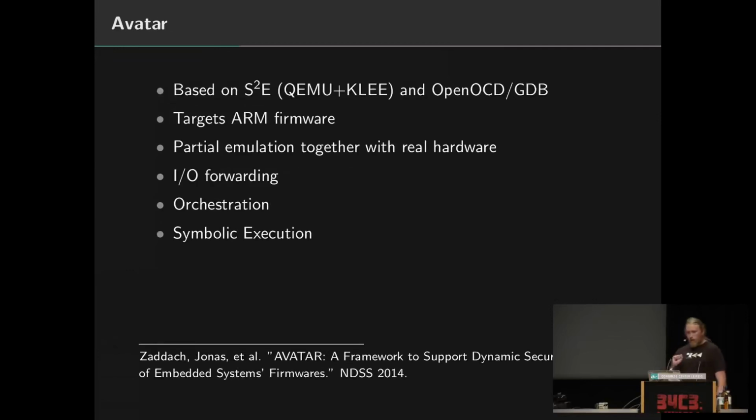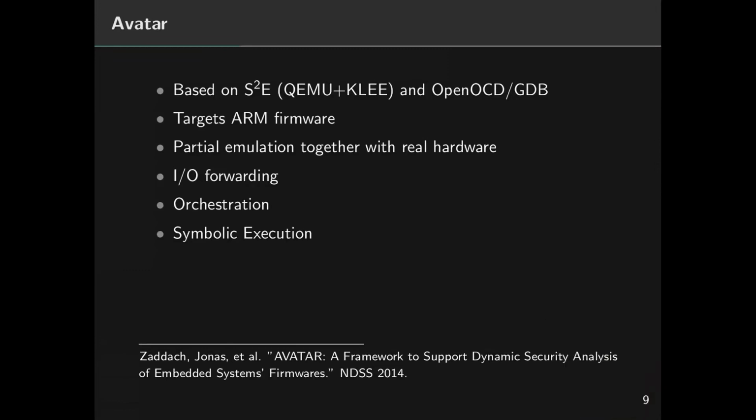So the last tool I want to talk about is Avatar, the first one. As some of you may have thought, if I'm talking about Avatar 2, there must have been a first Avatar. This tool was based on S2E, which is again a combination of QEMU and KLEE, which allows symbolic execution of QEMU-emulated firmware. Additionally, Avatar utilizes OpenOCD and GDB and allows partial emulation of ARM firmware.